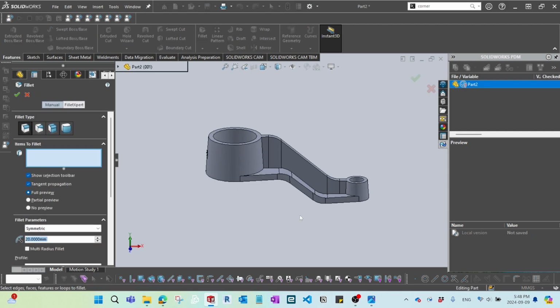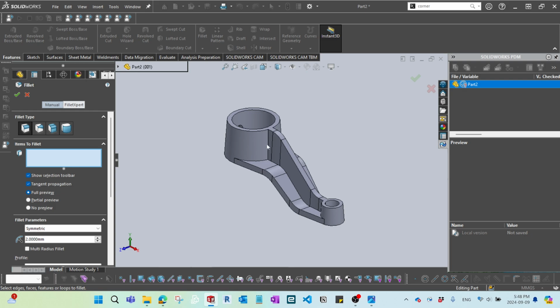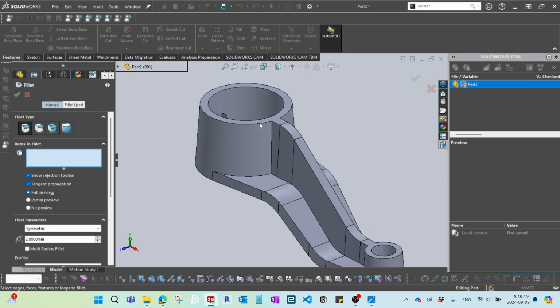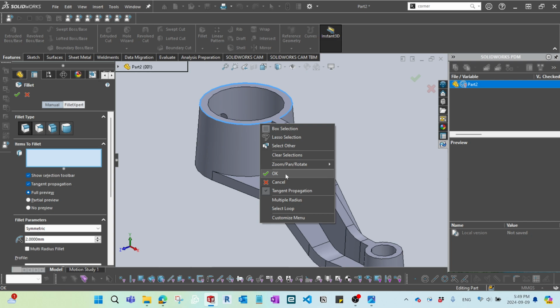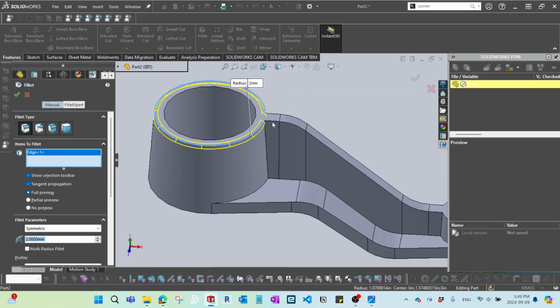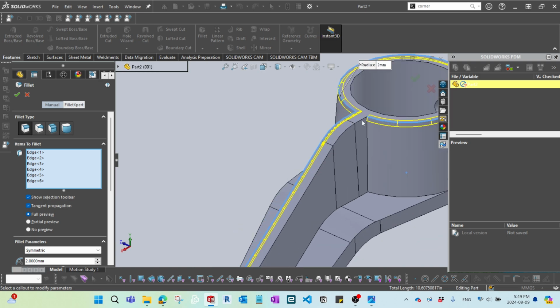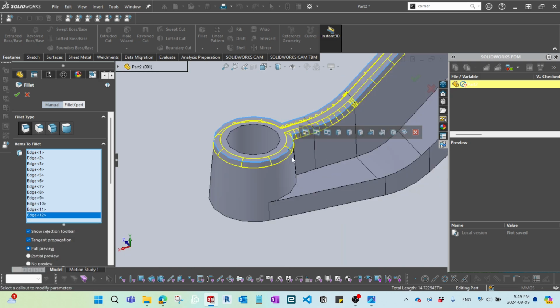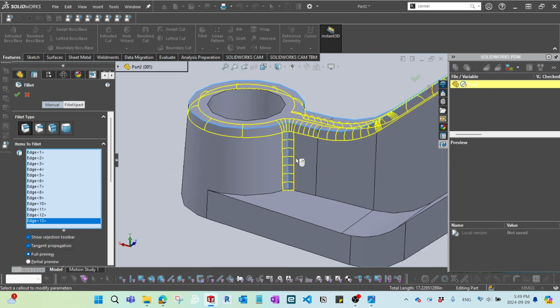So I'm going to go to the fillet, and we're going to apply a 2 millimeter fillet to the entire area. All those red spot areas are supposed to be radius 2 millimeter, so every spot of the fillet should be 2 millimeters. So I'm going to apply this point, and then select tangency. I'll apply select tangency one more time here. I'm going to grab this point, and I'm also going to apply this one at the corner.